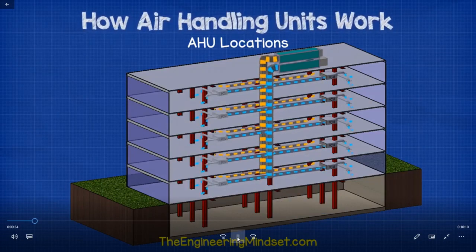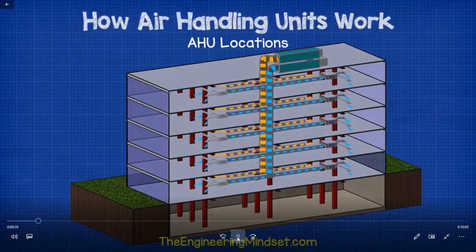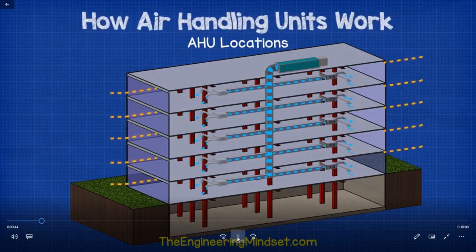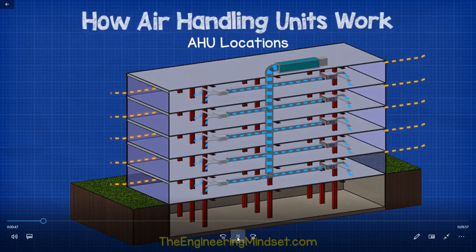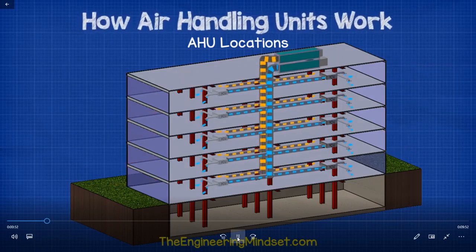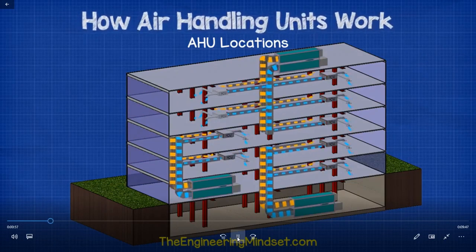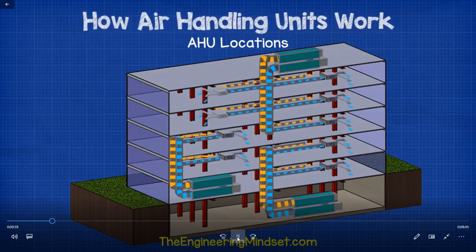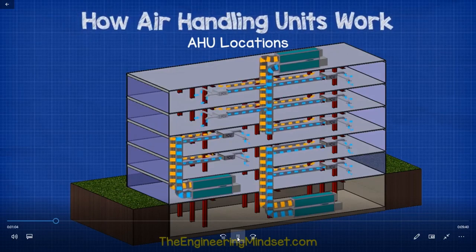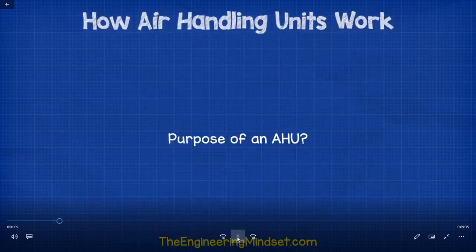Some buildings, particularly old high-rise buildings, will have just one large AHU, which is usually located on the roof. These will supply the entire building. They might not have a return duct. Some older designs rely on the air just simply leaking out of the building. But this design is not so common anymore in new buildings because it's very inefficient. Now it's most common to have multiple smaller AHUs supplying different zones to give better control and higher quality space conditioning. Buildings are now also much more airtight, so we need to have a return duct to regulate the pressure inside the building. So what is the purpose of an air handling unit?